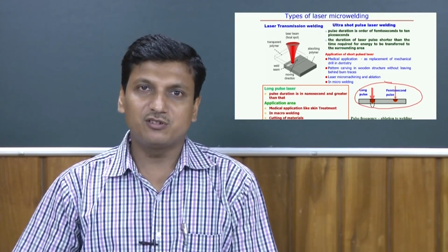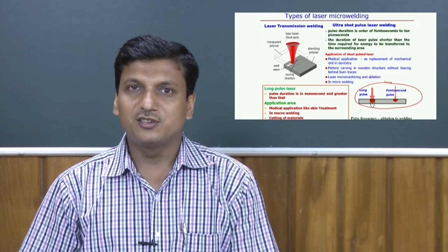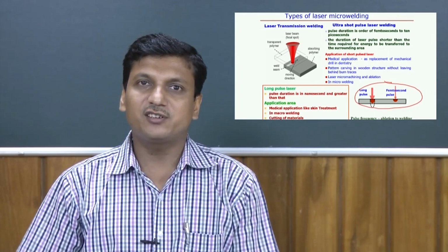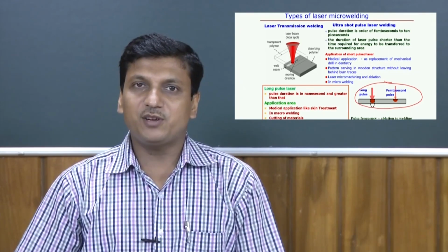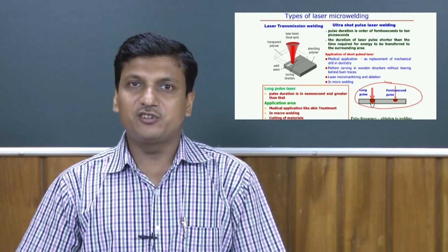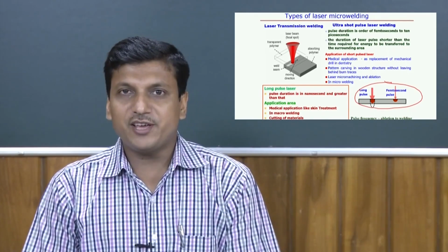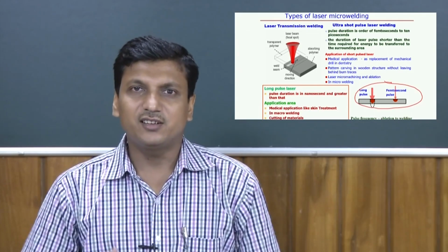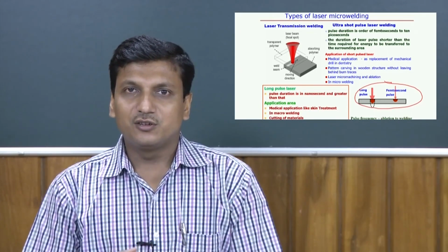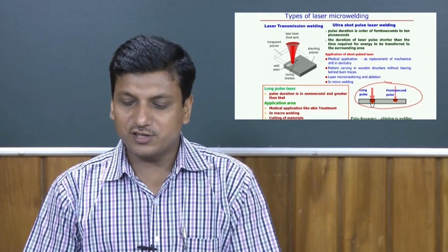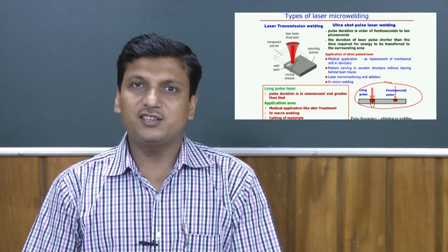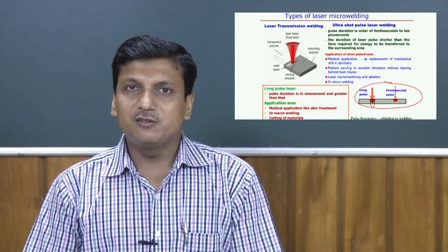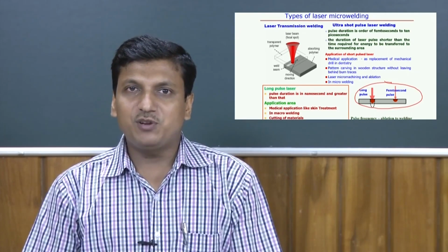because frequency is low means within the small time gap there is an application of a continuous pulse energy. So that energy actually ablates the material without affecting the surrounding material. But on the other hand, if pulse frequency is very high, say in the range of megahertz, then this femtosecond laser is more suitable for the welding purpose, because the application of the